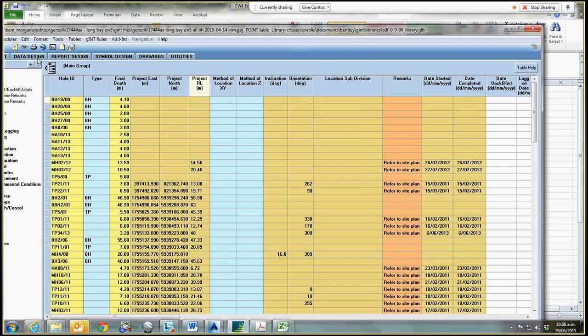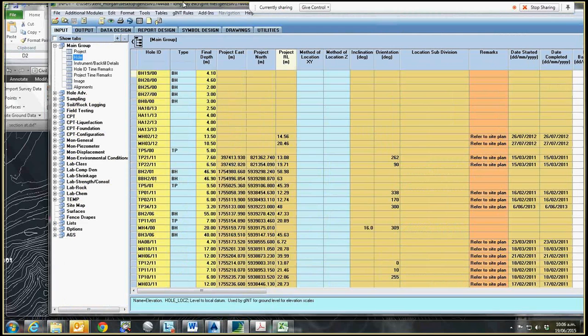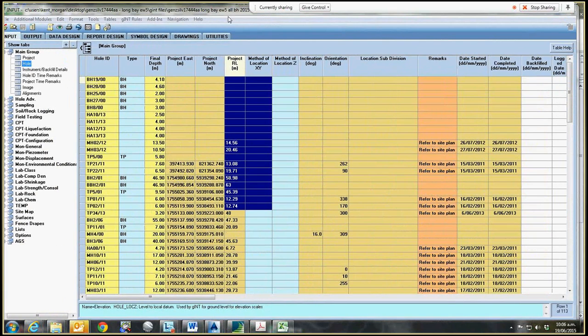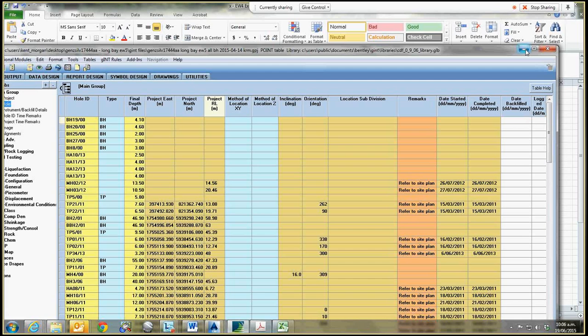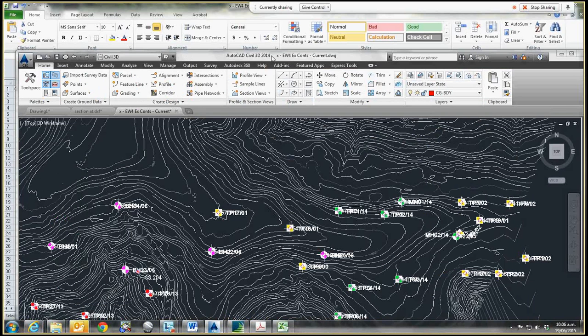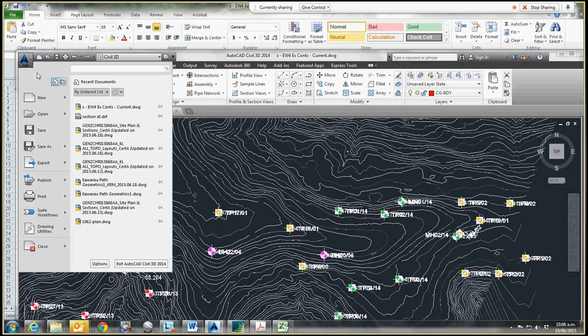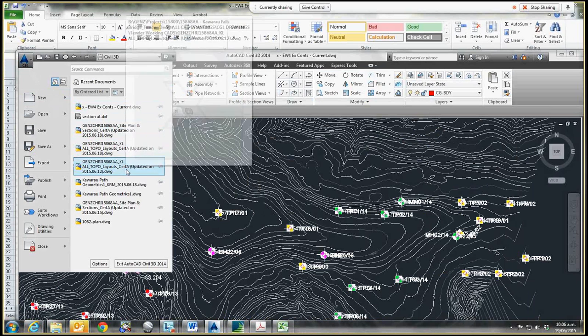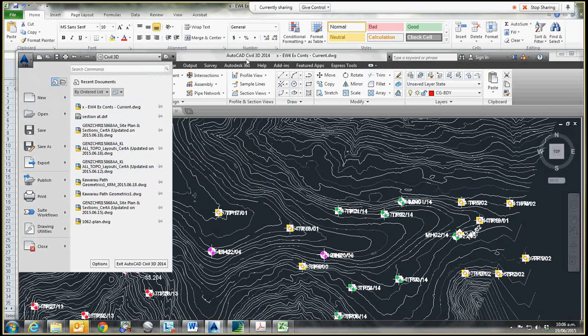In Civil 3D you can project objects to the profile. So yeah, that's how I was doing it, because then I just get the point and the label and the offset from Civil 3D, and then I get the fences from GINT. So I was just using GINT as just outputting fences. But yeah, that's really helpful. You told us today that you can get it on a different elevation. So yeah, probably easier that way. Yep. Very good. Cool.